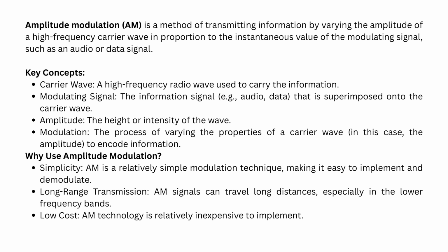If you're talking about its negatives or its cons, there is interference. AM signals can easily pick up noise from electrical sources and atmospheric disturbances. So that's one of the drawbacks of amplitude modulation. And when you talk about the audio quality, they often suffer from lower audio quality, with issues like hissing and fading. The next one is the limited frequency response, which can affect the clarity, particularly at higher frequencies. So that's another drawback of AM.